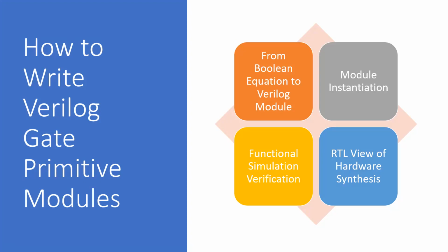Right, we'll see that that's equivalent to using a block symbol if you're doing a schematic interpretation. We'll also run a functional simulation of our modules to verify that they work. And then we'll use an RTL viewer to show the hardware that's actually synthesized in our design.